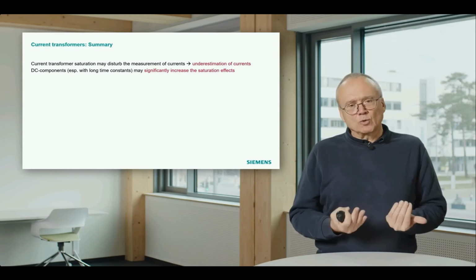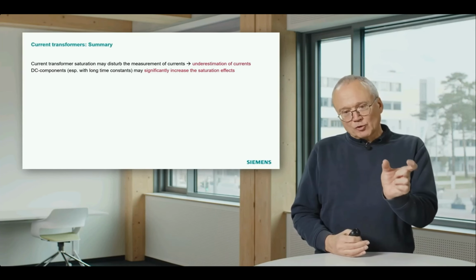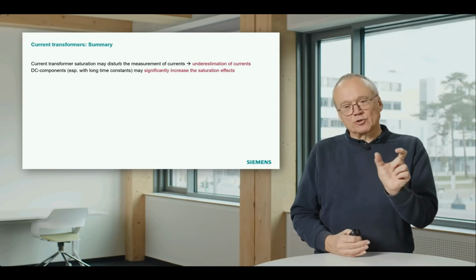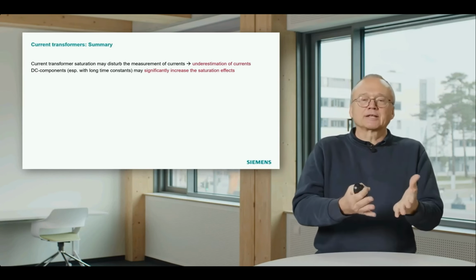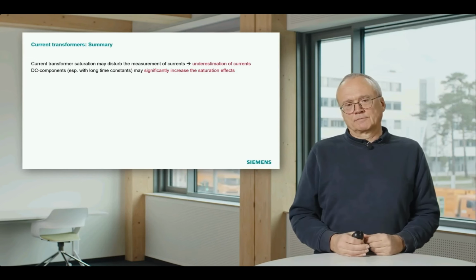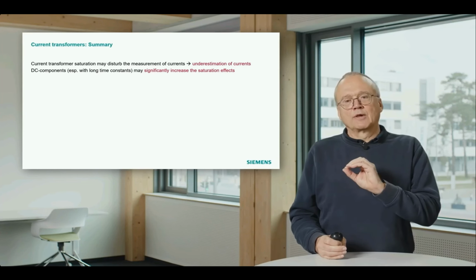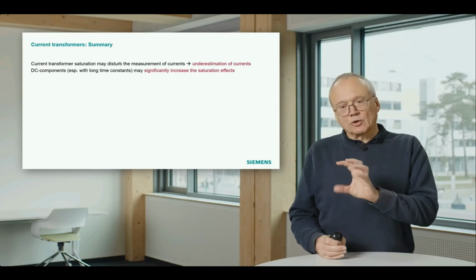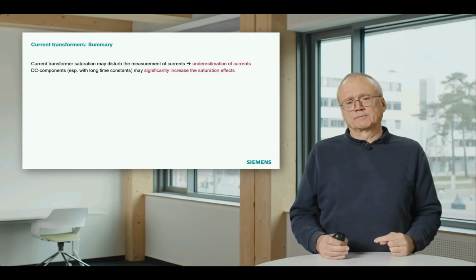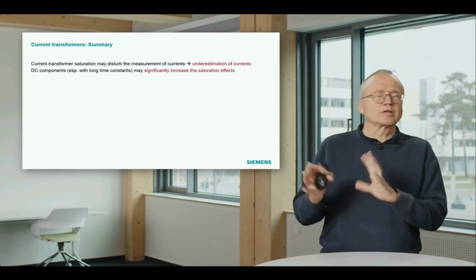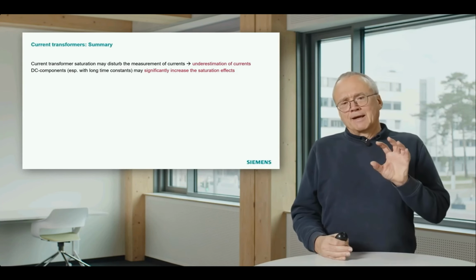If you design a distance relay, for instance, you may try to use measurements from that interval for a fast trip. But theoretically, you always have a risk of a missing or a delayed trip. You typically have no risk of a wrong trip. There are theoretical cases where you can even have a wrong trip, but normally it's a missing trip.